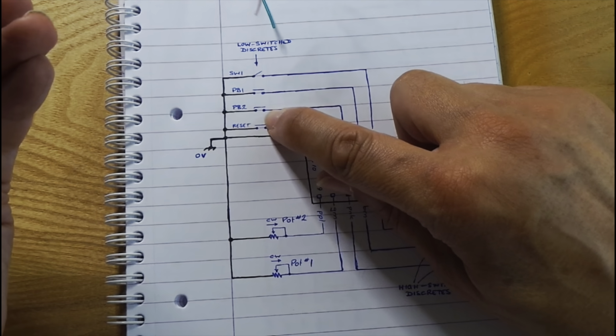You don't have to connect these again. If you disconnect these altogether, then you'll just get maximum brightness because you have a high resistance between pin 7 and ground. Pin 8 is a grey wire. It's another ground switched connection, and it's the second from the right on the top row. And if we connect that to ground, it will just reset the unit.